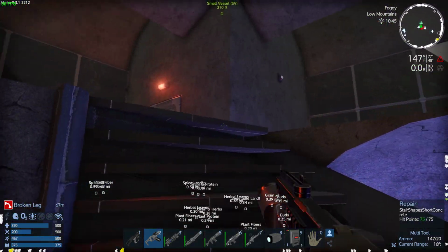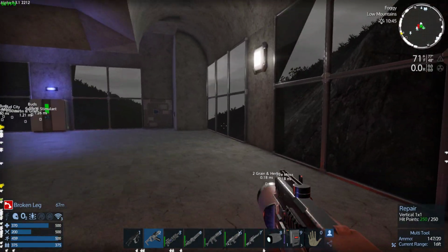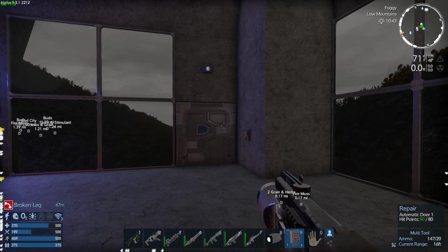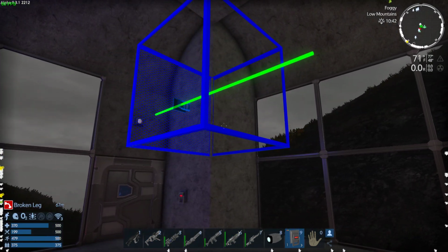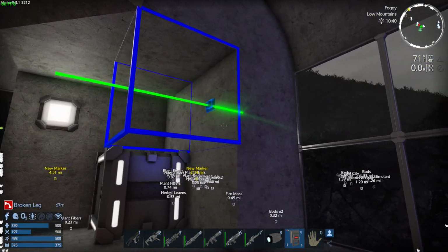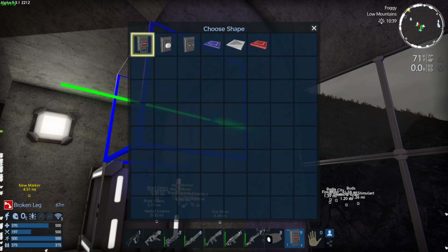Now, when you're deciding what switch to use, oh, you see the lights come on there, motion sensor. Basically, you select your general universal switch, and then you right-click, and this lets you select whether you want the toggle switch or the motion sensor.